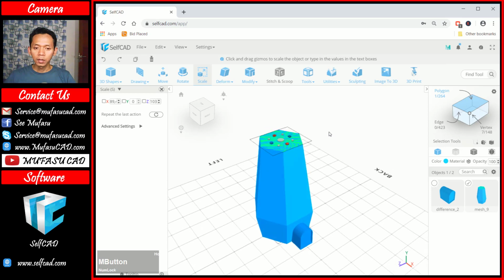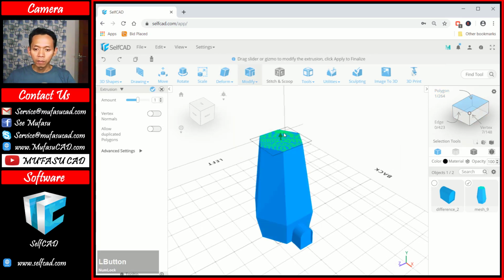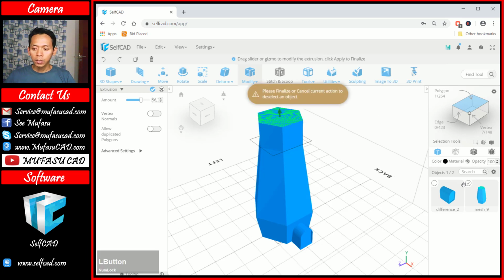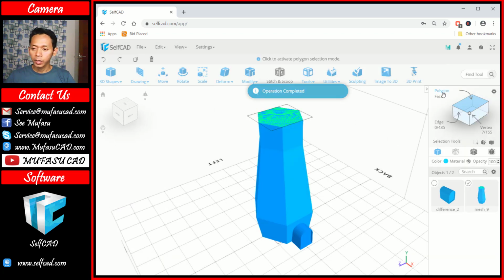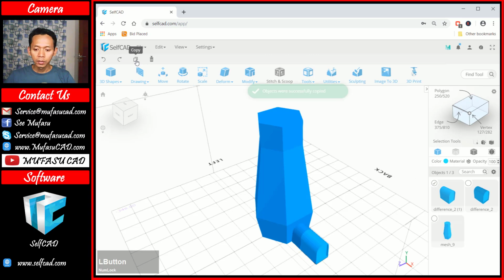Next, we can extrude. Okay, you can click modify extrusion. We extrude to the top here, okay, to this point. Next, we can copy this object. You can click OK first, and then you can uncheck this polygon. I will select this object, okay, and I will use a copy command. You can click here, copy.